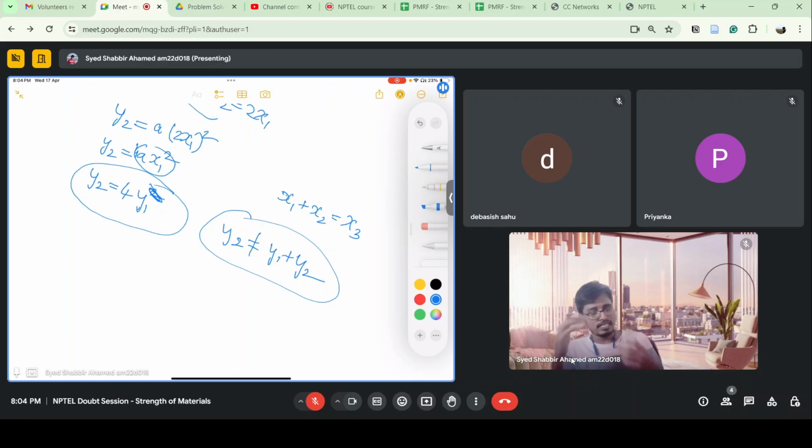Sometimes you might have an elastic material, but this curve is not linear. Okay, then this is also non-linearity. Even if you load it, it might come back to the original state, but it is not a linear relation. I cannot give you one elastic constant. I cannot give you Young's modulus for this material. So for the entire analysis, you cannot use superposition. You have to do other very complex things, advanced processes.